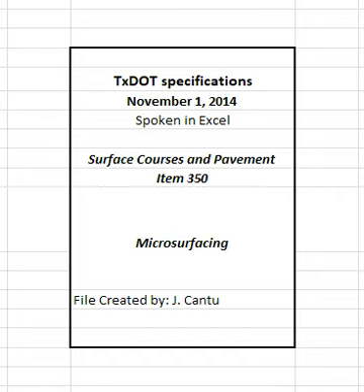4.8 Placing. Make necessary adjustments so that the mixture will have sufficient working life to allow for proper placement at the predicted ambient temperature and humidity. Spread the mixture uniformly to the lines and grades shown on the plans or as directed by means of a mechanical type spreader box. Shift the spreader box when necessary to maintain proper alignment. Clean the spreader box regularly to prevent buildup from occurring and to minimize clumps. Set and maintain the spreader box skids to prevent chatter in the finished mat.